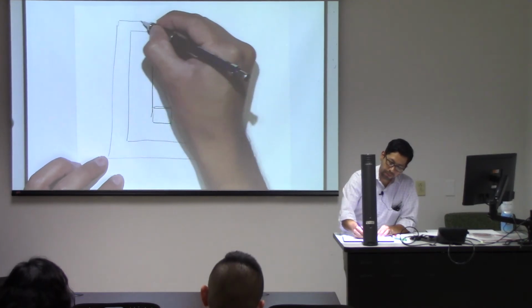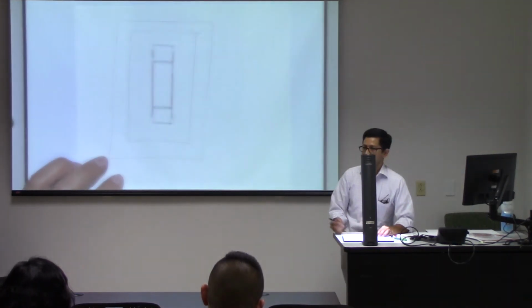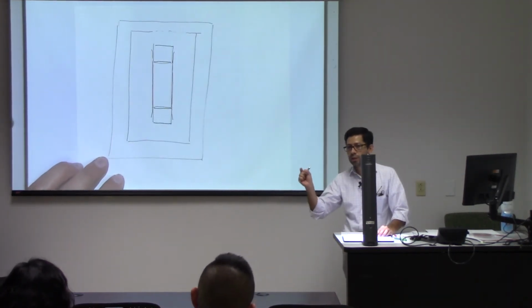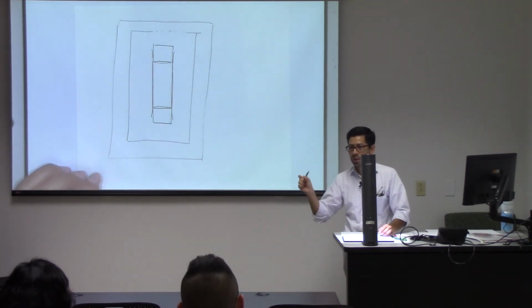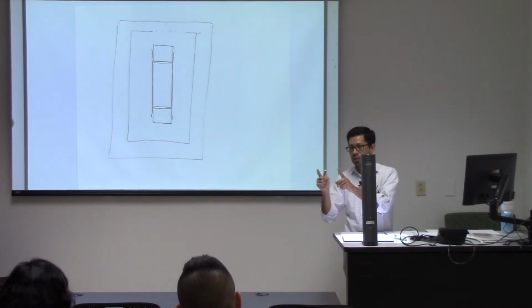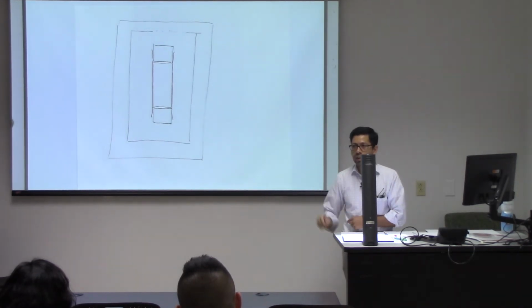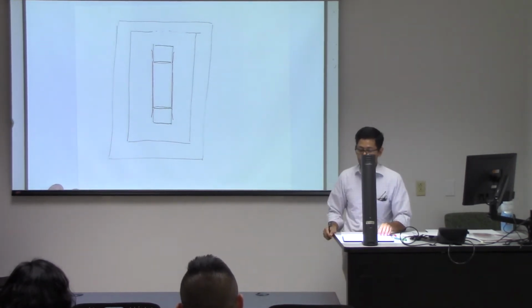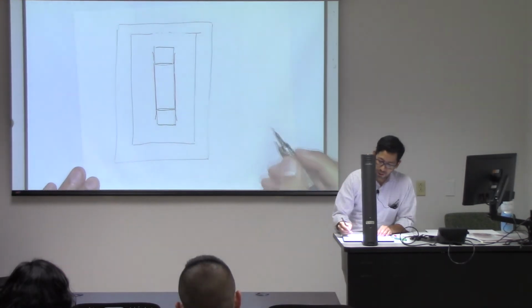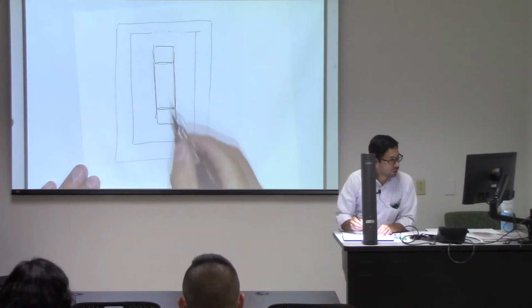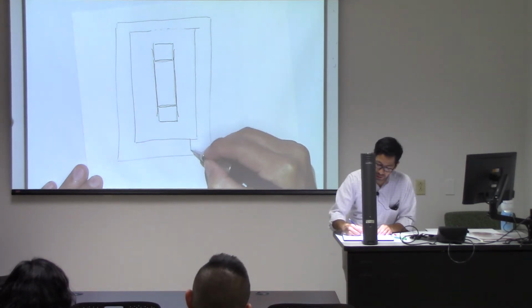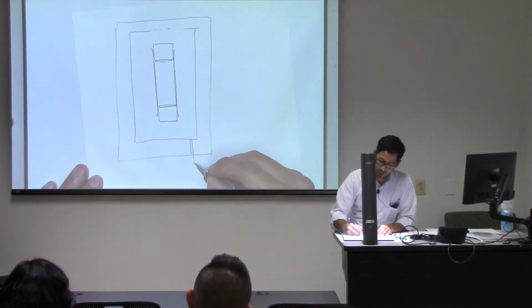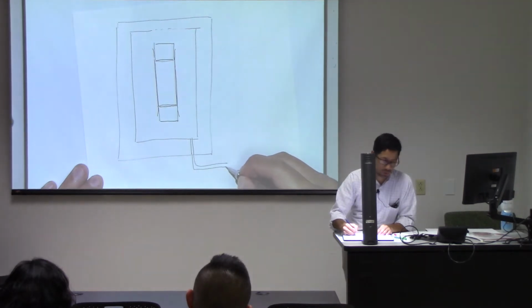In the lab, the pressure vessel that you're going to use has about a 1/2 inch wall. In my lab, we have a pressure vessel which is about 3 inches of thick steel, so you can go to very high pressure. If you want to increase the pressure in here, you'll have to make a hole somewhere and connect this to a pump.